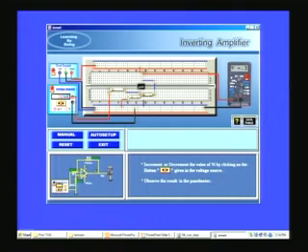30 millivolts means 300 millivolts, 10 times more. 40 millivolts gives me 400 millivolts or 0.4 volts. So you can see if I keep on increasing to larger values, then you will find it can also saturate at some stage, because the output voltage cannot be more than the power supply voltage. So this is the inverting amplifier. You can see also the voltage is negative.